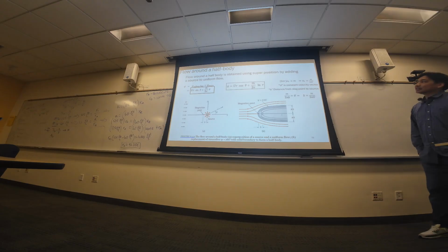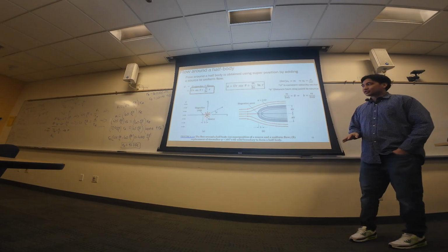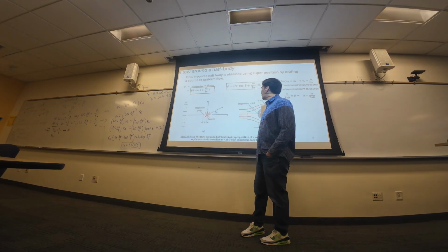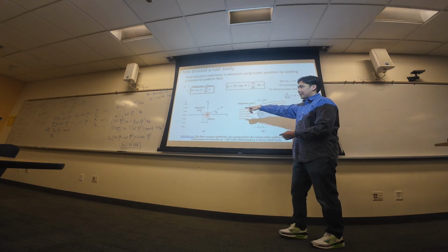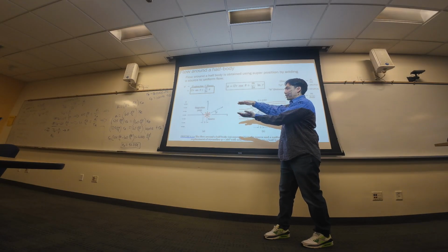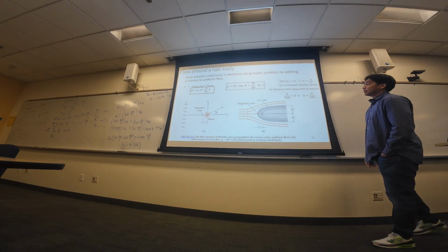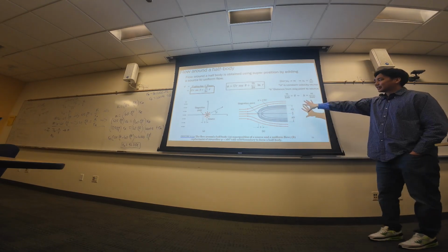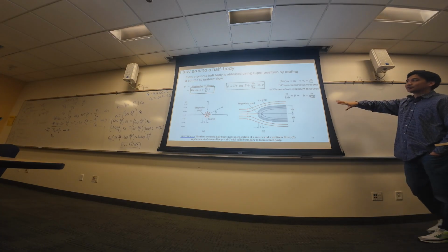A half body, to get this flow, is obtained using superposition by adding a source to uniform flow. So our two scenarios, right? Our source is just our flow vectors radially going outward. And then our uniform flow doesn't specifically show here, but that's just our capital U parallel velocity vectors going in one direction. They're not crossing. We just say half body, I believe, because we're only doing analysis on the front part. We're not caring too much about the other half, because something else happens there, which are different equations, so we're only going to focus on the first half of the body.